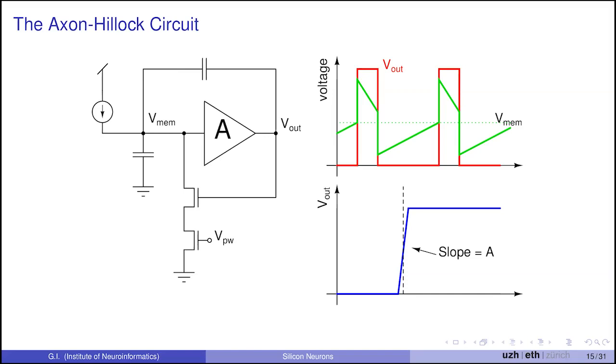One can either make single transistors very large, or one can make large transistors, and then to further reduce the device mismatch effect, make copies of those to either increase the effective W or increase the effective length, depending on whether you put them in parallel or in series.